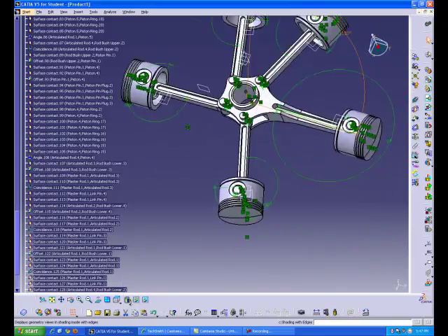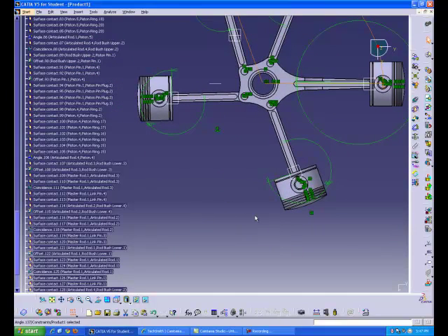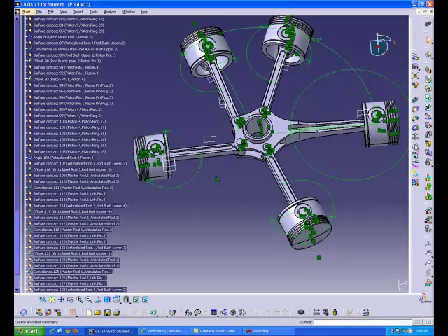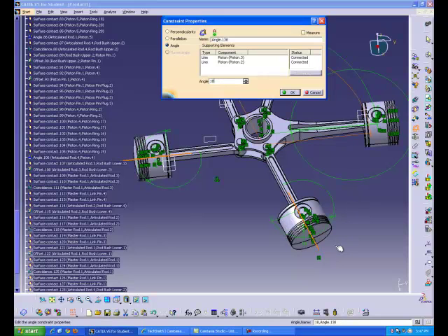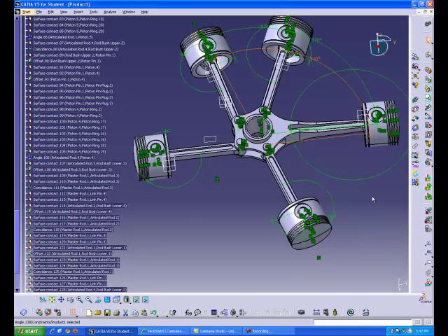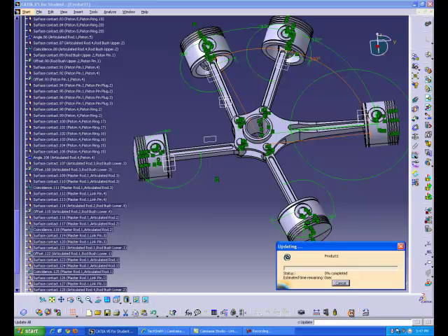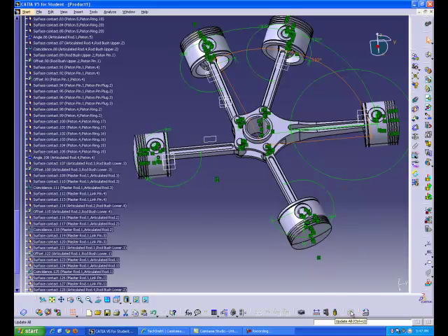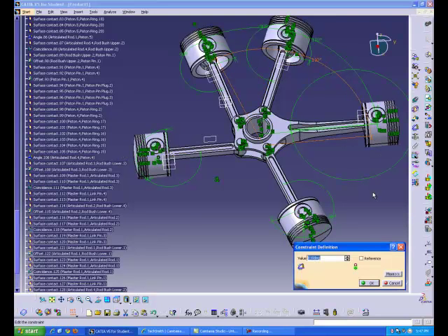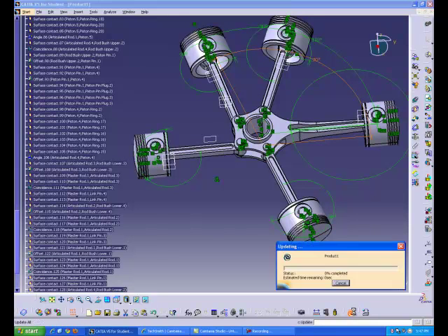The easiest way to look at this is if you go in the top view or look at it from the top somehow. We're going to do another angle constraint between the next piston and the piston after that, and that's not at 70 degree end. If you do like before and type 180 minus 70, it won't give you the right angle because this time it's measuring something different. It's actually measuring the proper angle, so double click on the angle and type in 70 and click update.